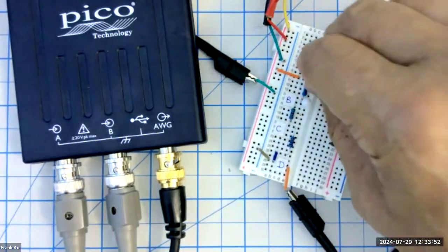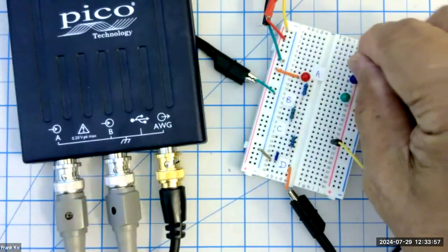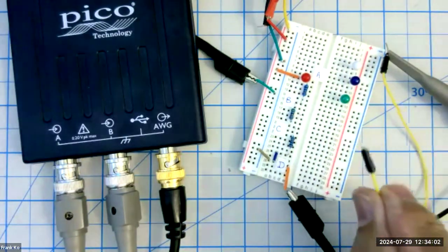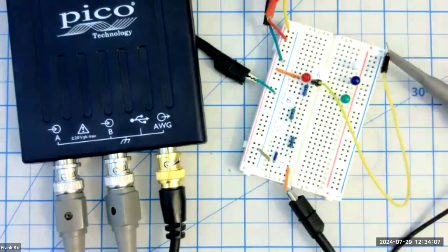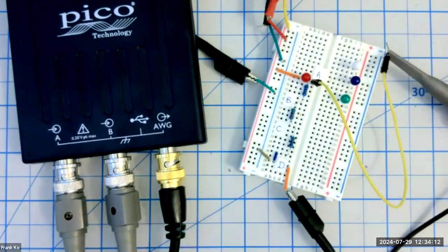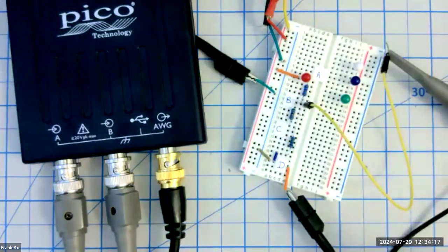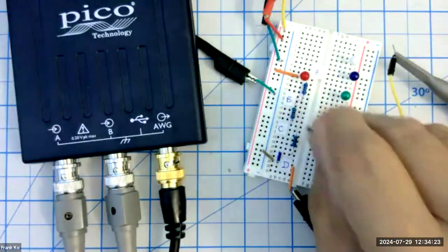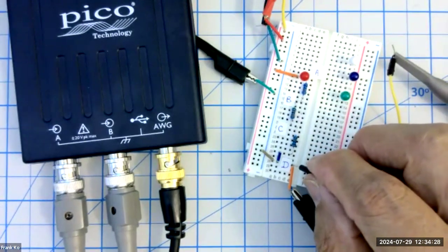And let me move this out of the way. That will be my point A. I'll just leave this one out here for the time being. And that's great. So if I wanted to measure at point A, I take this yellow jumper wire connected to my channel B oscope, and I will measure, boom, at point A. So this is my technician test point of voltage measurement, V at point A with respect to ground. My B at point B with respect to ground is here. My C at point C with respect to ground is right there. And my D is right here, which is basically ground. I should have a flat line on the oscope.